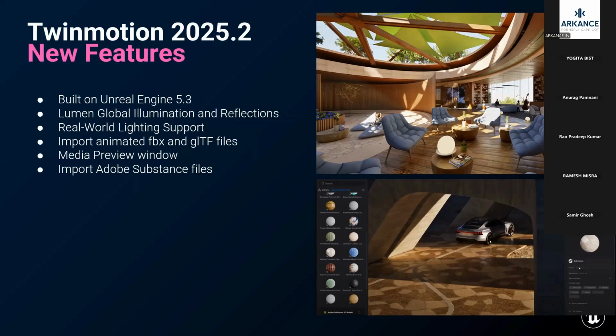The most common animated formats imported into the system are .fbx and glTF files, and it also supports .obj files, which are not animated. The only basic difference is that FBX is quite lower in size compared to OBJ, and OBJ sometimes doesn't export the real textures. Whenever you take a model from a particular solution to Twinmotion, it has a hierarchy-based or material-based structure.